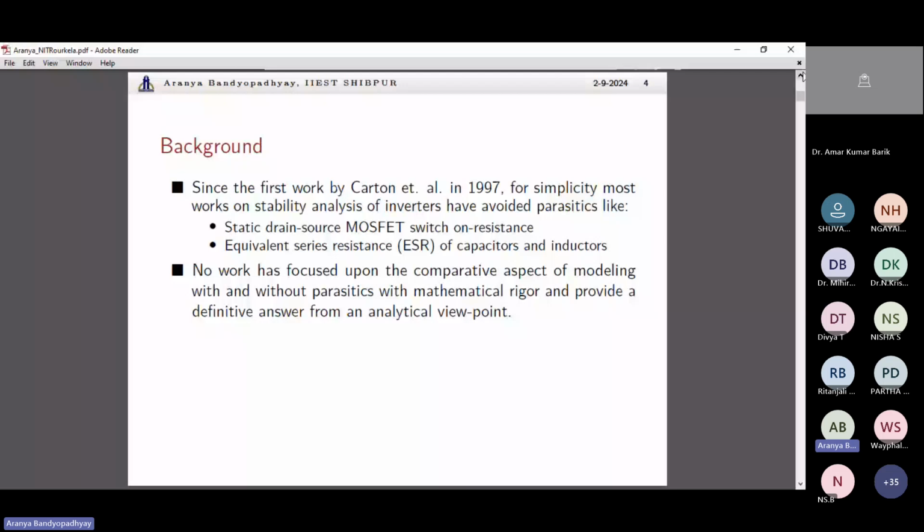And the effect is much more profound. In the case of low power circuits, you can say that we can basically avoid the effect of ESRs of capacitors when the voltage level goes high, and you will be right to say so. Why? Because if you just go through the data sheet, you will see that when the values of the capacitors increase, its ESR basically decreases.